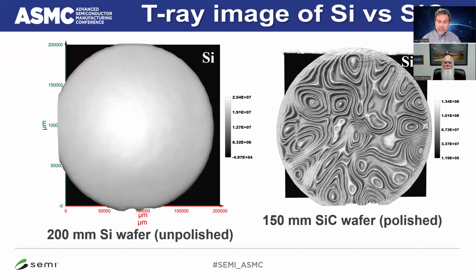So polytype variation may be a little bit, but silicon carbide is the most frightening kind of semiconductor. It has some 250 different polytypes. So it's good that industry can produce only one or two different polytypes. 4H and 6H are the most common ones. There's another one, 4R or something, I forgot, or 2R. Anyway, it's in the paper.